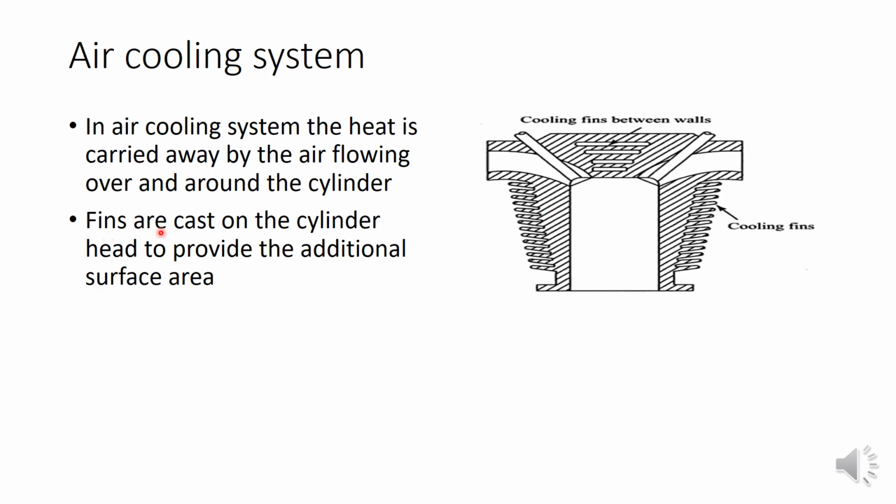What is fins? Fins are a number of thin plates or smaller thin plates attached to the cylinder wall, made of mostly aluminum or highly thermal conductive material. And its function, already we have discussed the heat transfer. Here also the heat transfer is by convection. So convection heat transfer means we are transferring heat from one fluid to other. So we are transferring heat to the air outside from the gas inside the engine.